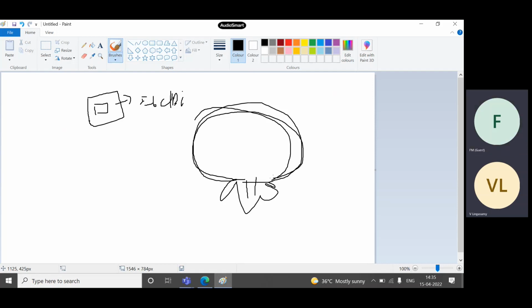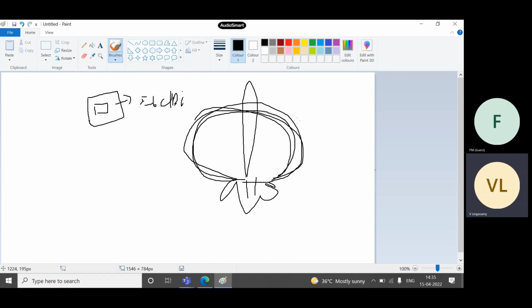Now if you want gain, what does that mean? Gain is actually directivity, right? So how we are focusing the energy in a particular direction. High gain means high sharpness towards a particular direction, which means we are focusing all the energy towards that direction. What happens here is we are distributing the power in many directions. Therefore, the coverage range will be very limited.